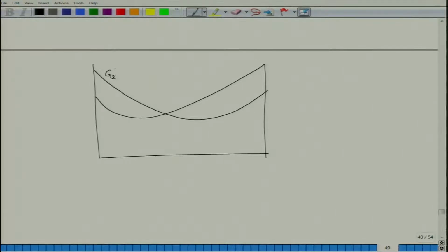This is G2 of liquid, this is G2 of solid. Now last time we considered the composition here, so that is mu B L, this is mu A L, and every time we see that any composition starting from M and N would not lead to solid phase formation, because every time I see that in order to form solid I have to increase the free energy.